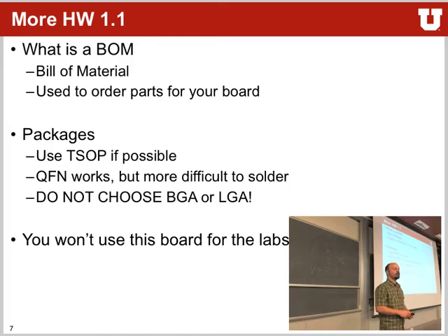If we actually do use DIP, who's going to drill the holes? Us or the... Oh, the manufacturer. Yes. No, you're not drilling anything. That's actually what you're doing in the layout design. So once you design your PCBs, you tell where you want drill holes, how big they should be, how much copper there should be around it, and the boards will come back like that. So don't worry about that part. All right. Absolutely do not choose a BGA or an LGA package. They are really hard to solder by hand. It's possible, but it's hard and difficult to do.